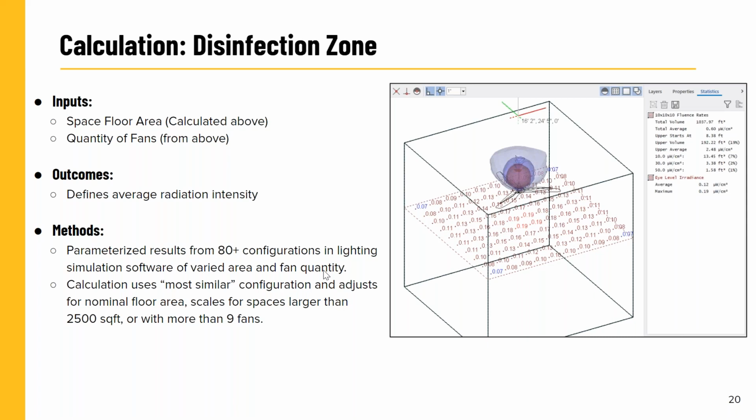And one of our first measures of a successful design in a UV system is achieving 25 zonal air turnovers per hour, which essentially means I exchange the air that the UV is influencing with the breathing zone or the air below it. If I can exchange those 25 times an hour, that is where you essentially start reaching diminishing returns. So 25 is our design standard.